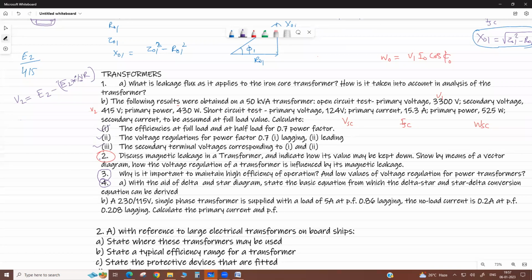So this is very simple. Tomorrow we will solve this; if you don't get it, try yourself. Okay, correct? Could you explain the second part once more? Second, when we calculate the voltage regulation in part 2 of this question, suppose you get 5% voltage regulation. Here in lagging it will be positive. In leading it may be, suppose, -2%, negative. Okay, on leading. Correct.